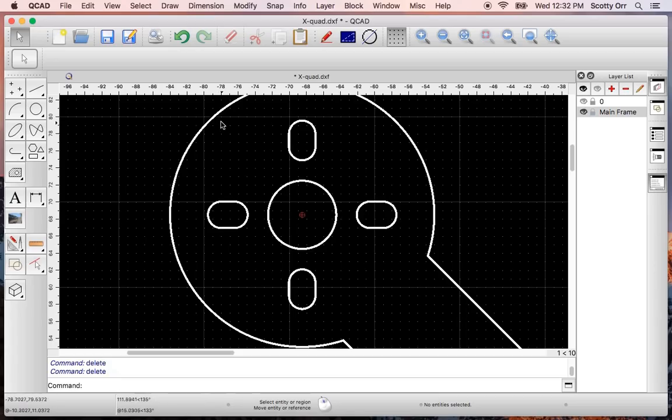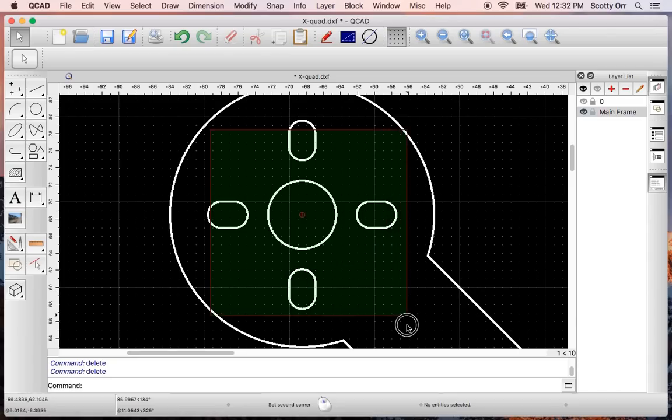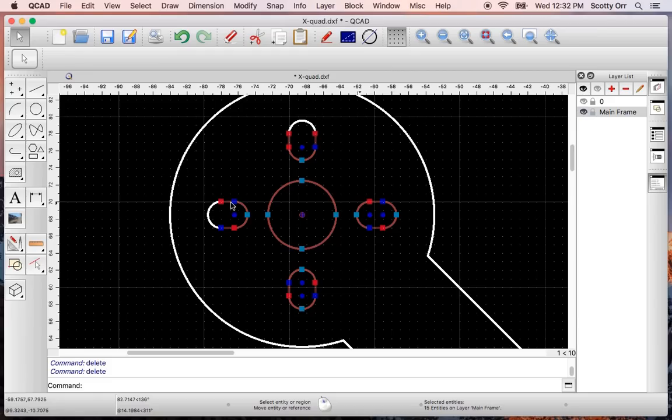Now, when you're selecting, you can click and then hold shift and click all the other spots, but you can also do a rectangular select just by going to some place that's going to touch all of those arcs. Okay, so I don't want to do the outside circle. So and then hold the left mouse button down and drag, and that should select almost everything. Notice it missed these. Now if I say shift and shift, now I've got all of that selected.